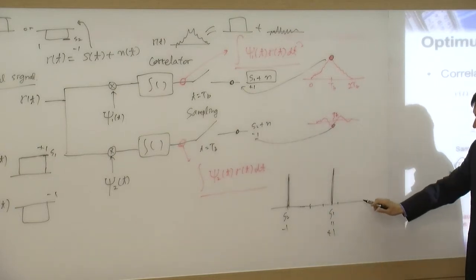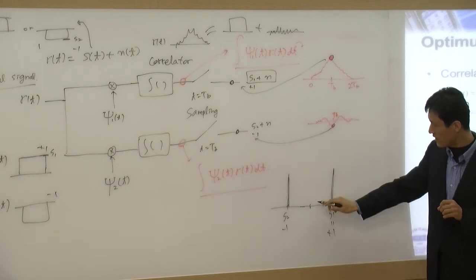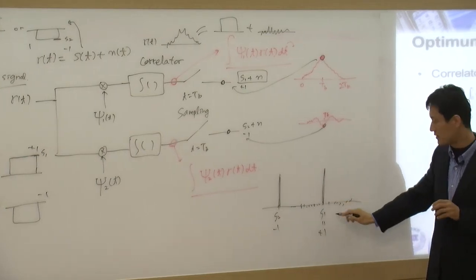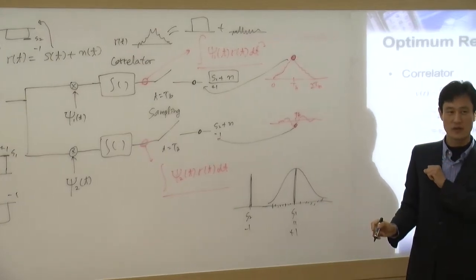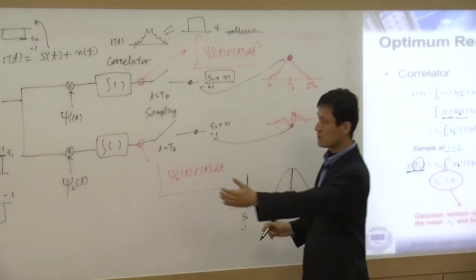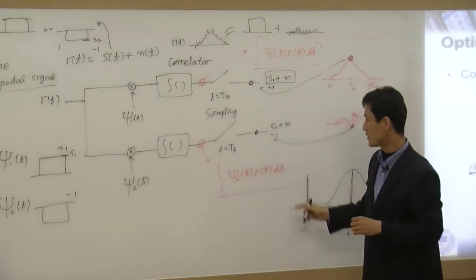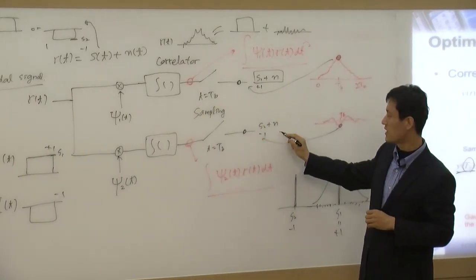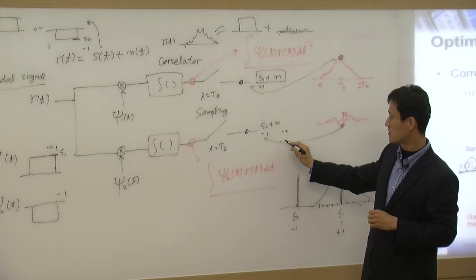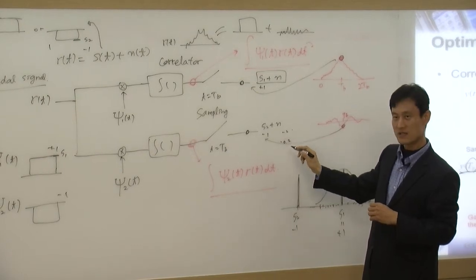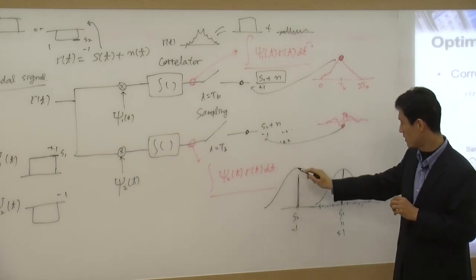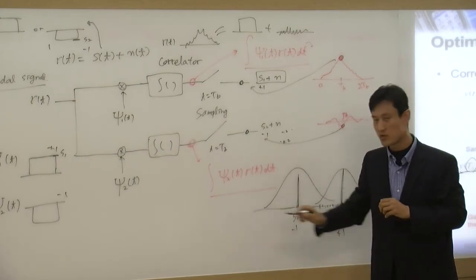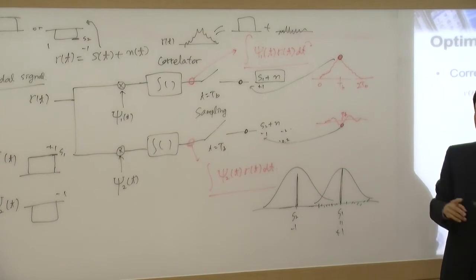Or sometimes a very high value, like 2. So over those million samples, you're going to get random values. You're going to get this distribution when you transmit S1. Same thing happens when you transmit S2. You never always get minus 1. Sometimes minus 2, sometimes minus 0.2, something like this, right? So you're going to get this kind of distribution when you transmit S2.